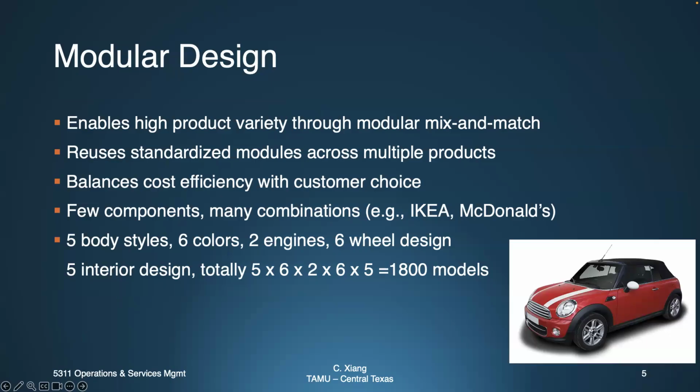We can also understand modular design more clearly using the QFD framework on the last page. If a customer attribute is primarily affected by one specific subsystem, that feature is modular. In contrast, if a customer attribute depends on many interacting subsystems, that design is not modular.